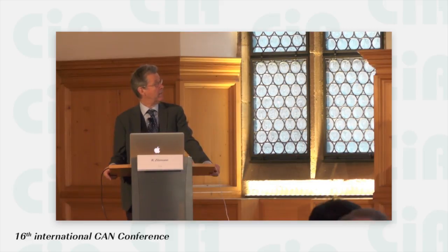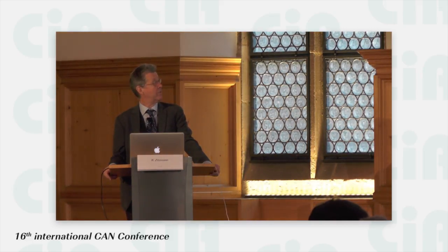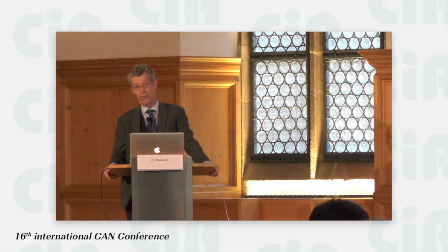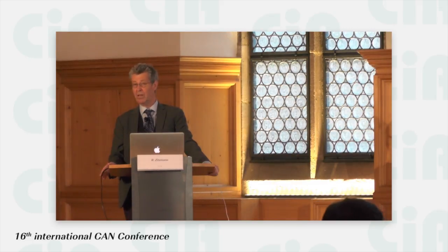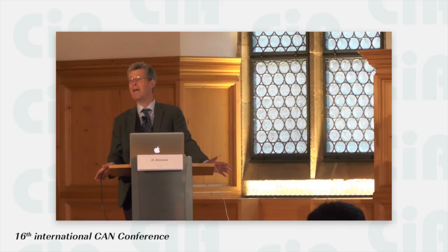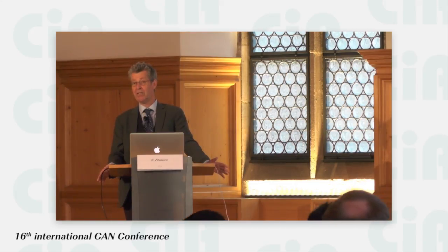What we did in the beginning was that we used for the very first time what is today known as the ISO 11898-2 transceiver chips. Because before 1992, everybody had invented their own physical layer based on RS485 with some modifications. The modifications made it impossible to connect one device to another device.